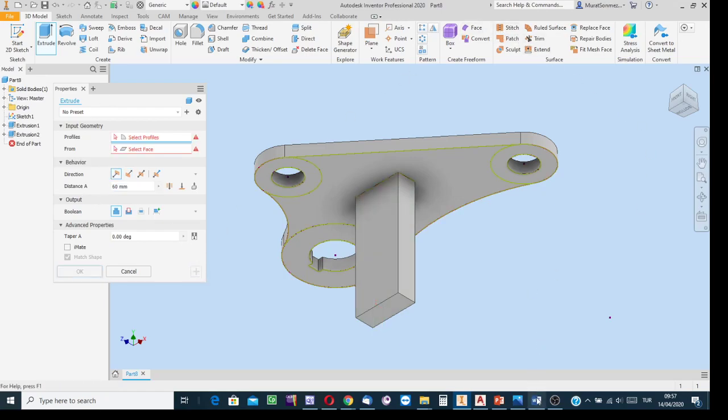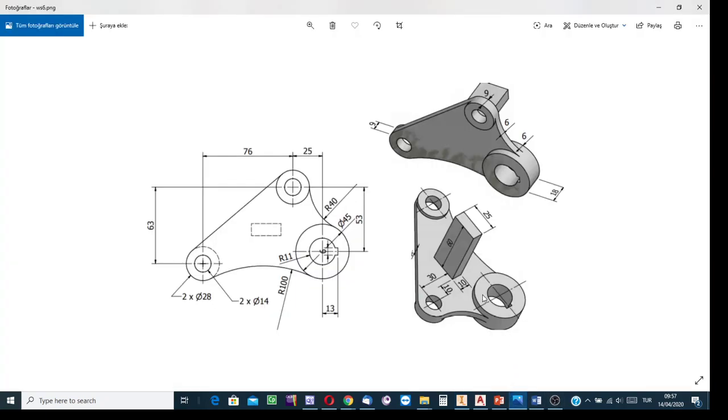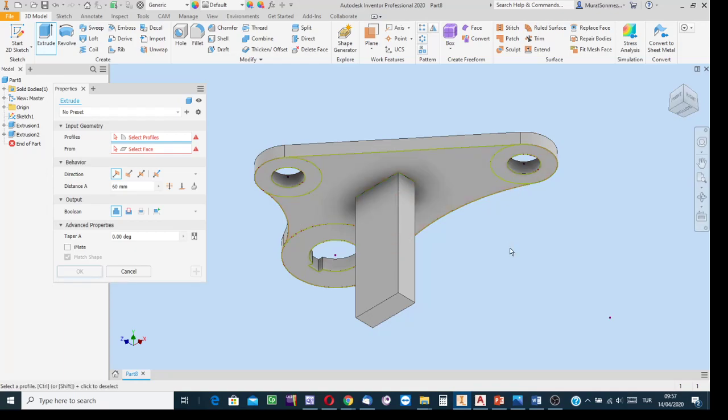At the back side of the prism, here and there, are 2 bosses. Create them. You see here the total thickness of this part is 9 units. The thickness of the main part is 6, so 9 minus 6, 3 units. Create this boss. Where is it?